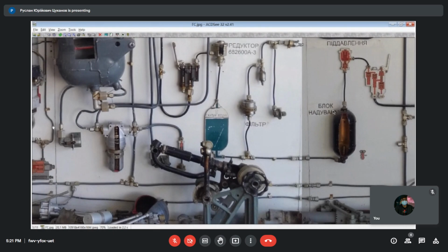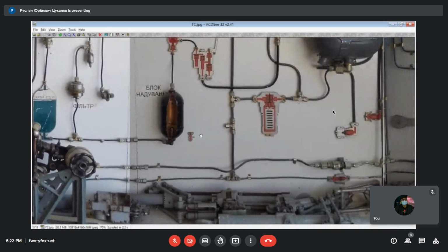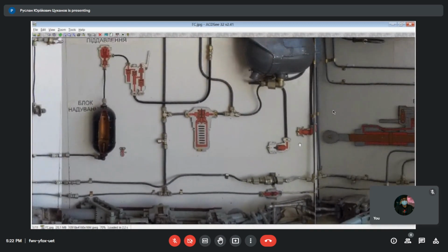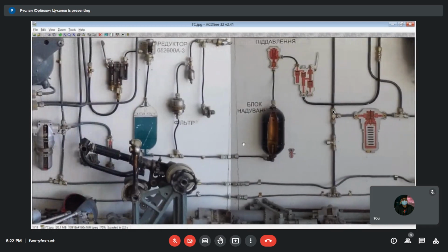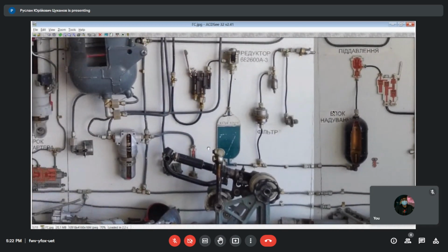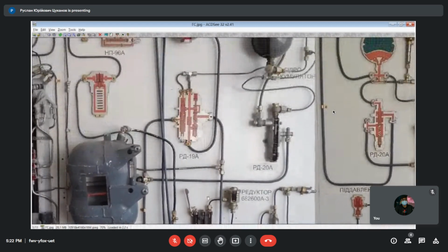So suction lines are made of aluminum alloy, pressure lines are made of stainless steel. They can withstand quite different overpressure. And in case of accidental wrong attachment, vice versa, you will destroy the aluminum pipelines by high pressure. So to avoid wrong connection of ground facilities, these fittings are made of different size. You can also see them here. You see here big diameter, here low diameter. It's a little bit more difficult for designers, but it guarantees that this problem can be avoided in operation.